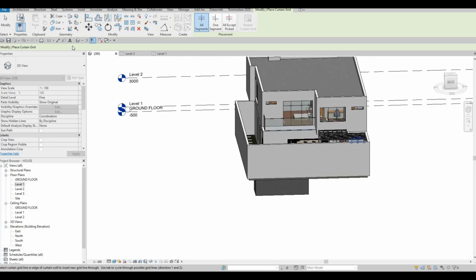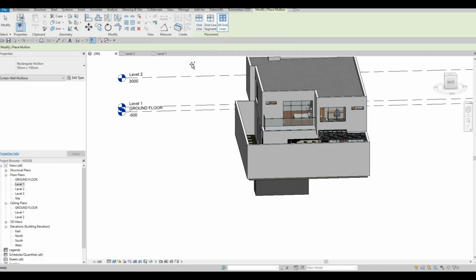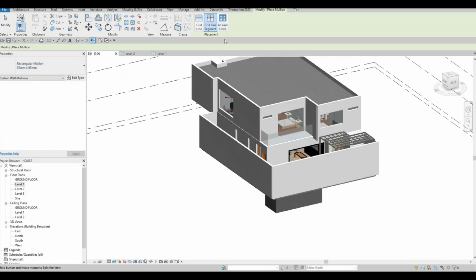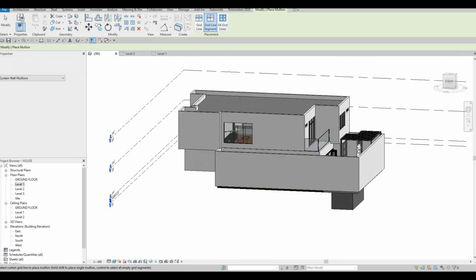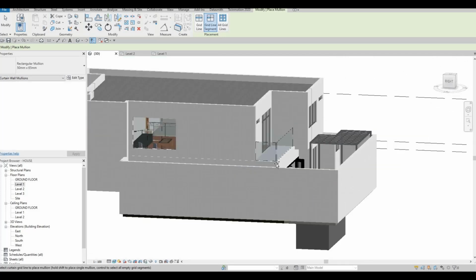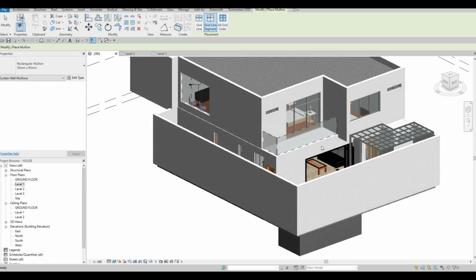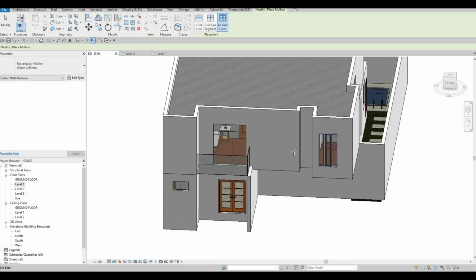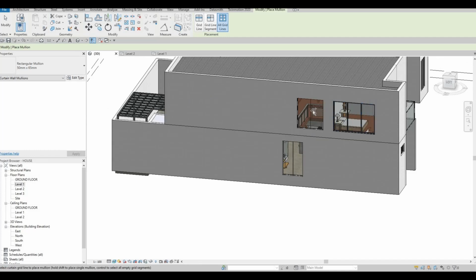already. What I'm gonna do next is go to architecture, add in mullion, and then here we could add in all grid lines. Let's change this to 50 by 65, and then click on all grid. So we need to just select those there, and wherever you put your grid line, your curtain grid, just select those. And as you can see, it's easy to select and everything will form by itself. And then once you finish it,